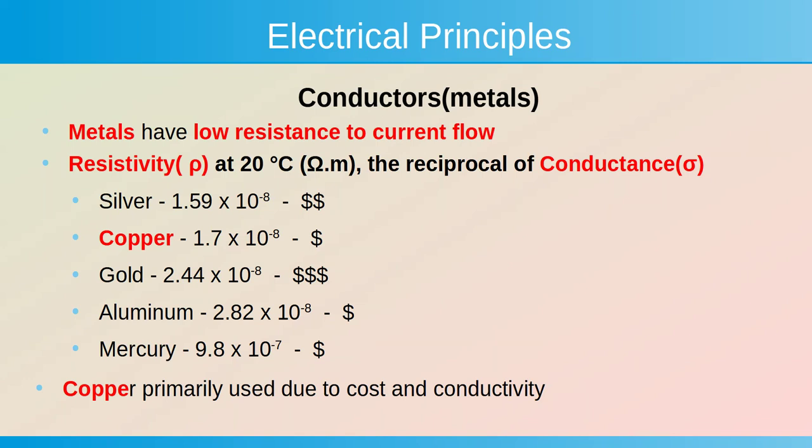I know at Oak Ridge, back in the days of developing the atomic bomb, some of that research there, they used a lot of silver wire because they had kind of an unlimited budget. But typically, we use copper for most things. You'll see gold-plated or nickel-plated conductor surfaces, sometimes silver on conductors. Problem is it tarnishes. So if it's not an airtight seal, it's going to become a bad connection over a period of time.